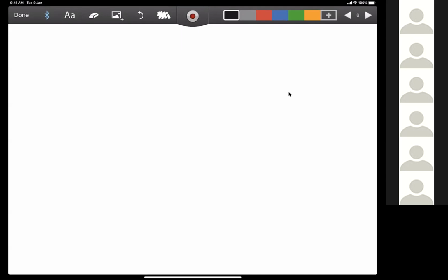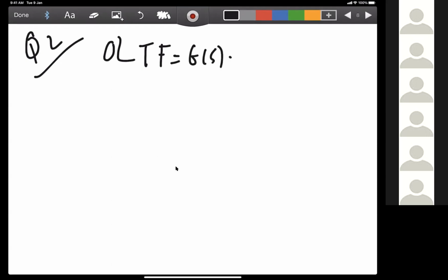So what is the open loop transfer function? It is the same as in figure Q2.1, because they said it is based on the root locus in the figure. We observe the plot. A very nice graph using Excel. So how many poles do you have there? 3. Any zeros? No zeros.